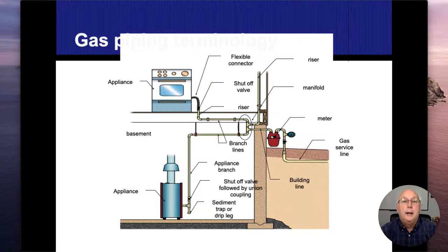All right. But he was explaining to me that they do have some issues where moisture and water gets in there, and you have to have that drip leg because sometimes they got stuck where the gas valves were in the open position and they couldn't shut down because of rust and corrosion that was there. That made a lot of sense to me, and it put a lot more importance on having a drip leg in there. All right. But mostly it's just to catch the garbage.